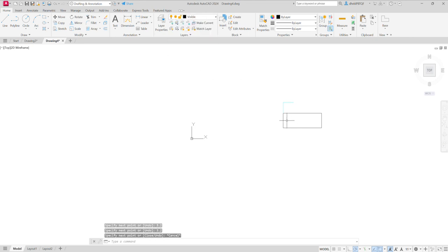I'm going to bring in my visible line, click on a line, and I'm going to bring that line up just like that. Make it go this way at 0 degrees, 4.4, and I'm going to bring it back to this corner, and I'm going to hit escape. Okay, great.